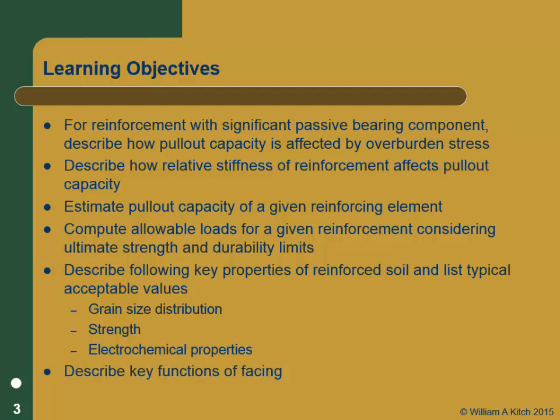And then you need to be able to describe what facing does for us. We don't really design facing. The facing is basically commercially available stuff, with the exception of if you're doing a shotcrete facing. But you have to understand its properties.